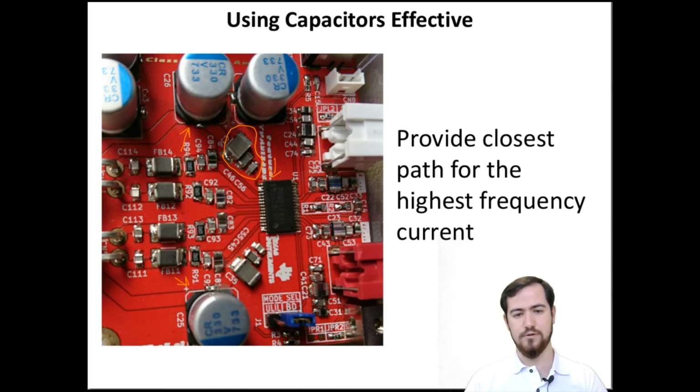It is also valid for the bottom part of this printed circuit board. As you can see, even for the ceramic capacitors, the smaller one has the higher bandwidth, so it is the closest one to our IC, and the larger ceramic capacitors are connected just next to the smallest one, as shown in this figure. Placement of capacitors is very important to overcome many problems that you can see during the operation.